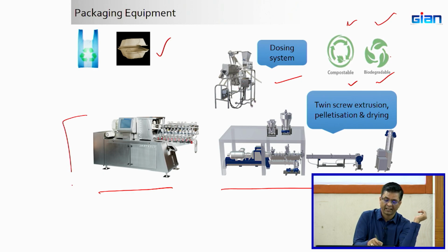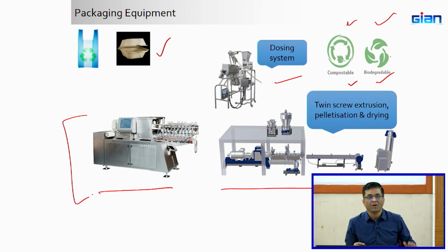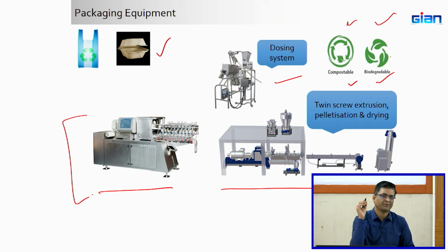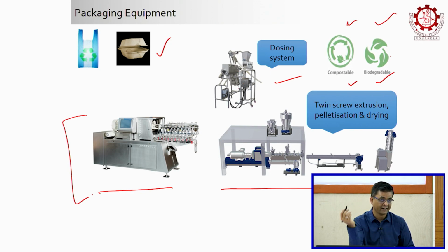And extrusion technology remains the same, whether you use it for making alternative snacks or protein, or to make polymeric materials. The only problem is if you are using it for polymeric material and then move on to food, cleaning is a big issue, because plastics are melted at high temperature, whereas food is at lower temperature. So, that cleaning becomes an issue.